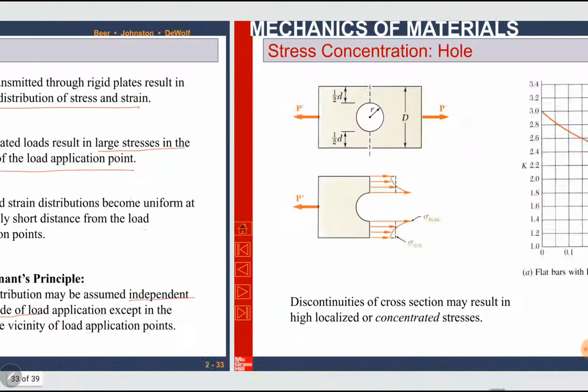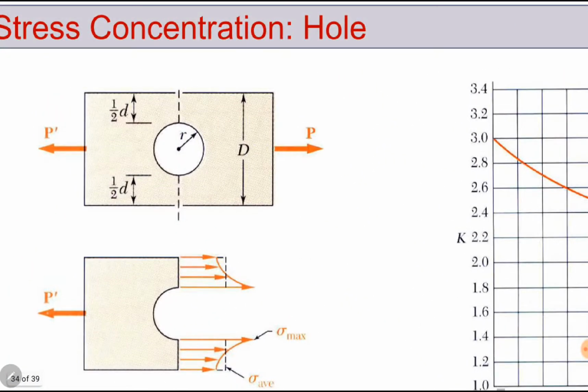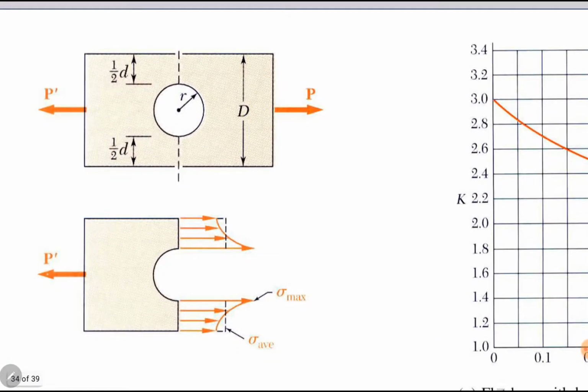Now we have some special cases to be discussed here. If we have a plate and there's a hole in the center of the plate, and force is being applied at the ends of the plate, we note that the maximum stress will exist around the hole because the hole is stressed up. It will be maximum where the diameter of the hole exists. These parts are stressed up.